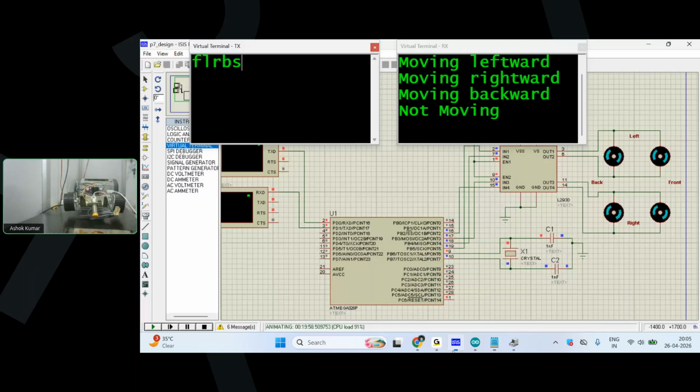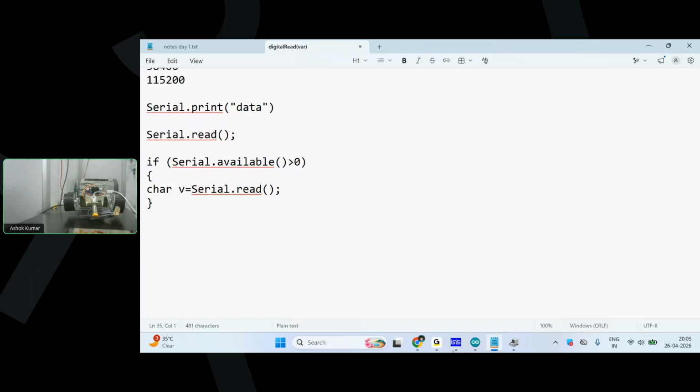But for that, first we need to understand how this analog works. Right. So the next topic is analog communication. As I mentioned earlier yesterday, we have a few pins, pin number 3, 5, 6, 9, 10, and 11. These we use for analog write. Okay, and analog write is not 0 or 1, it is 0 to 5 volt.